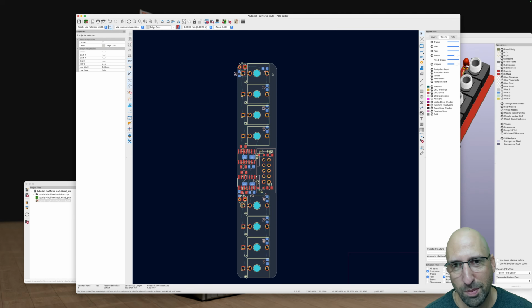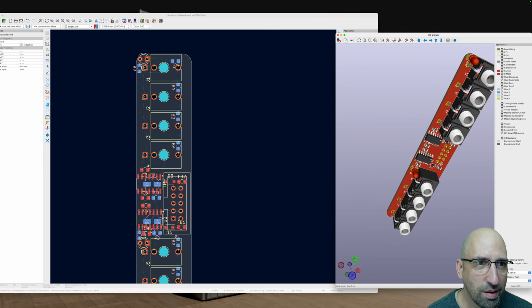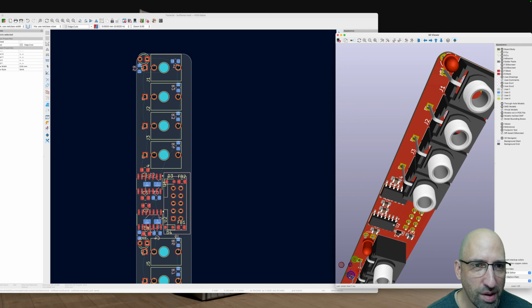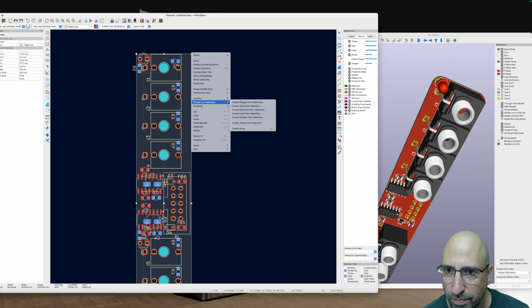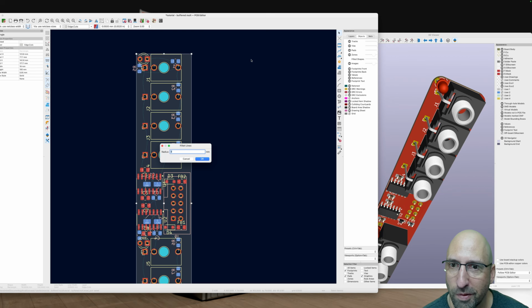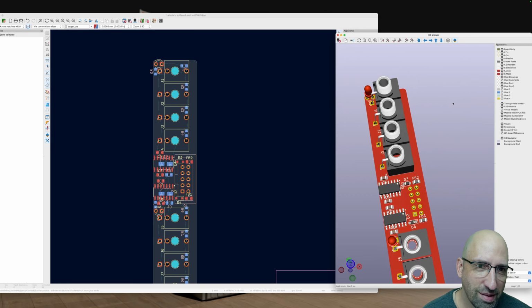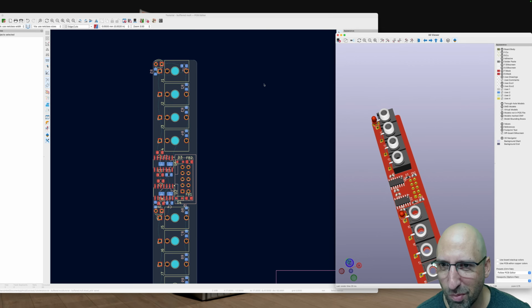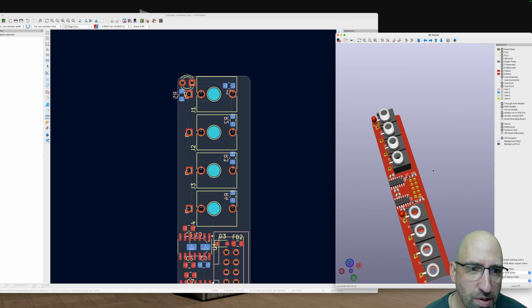And that feels a little bit too severe. I mean, maybe not that bad, but a little bit hectic. It's also chopping a bit of that LED pin off. So let's just undo that. Fillet lines. Let's go 1.5mm. Yeah, that's a little more subtle. Just so that it feels nicer when you're working with it. You don't get these jagged corners. All right, looks a little bit cooler as well, I think.